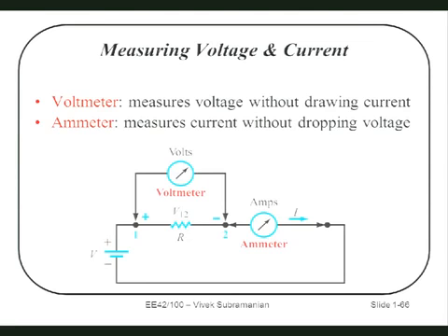That's pretty common. So a voltmeter should have a really high resistance. The idea being, if it has a really high resistance, it doesn't draw much current when it makes the measurement. So it doesn't draw much energy out of the system, so it doesn't perturb the system. So a voltmeter measures voltage, in an ideal world, without drawing any current. In practice, it draws a tiny amount. Actually let's say it's a 10 megohm voltmeter, and I measure a 10 volt battery. How much current does it draw from the battery when I measure it? 1 microamp. Good, I was just seeing if you remember those numbers. That's right. Okay? Okay, good.